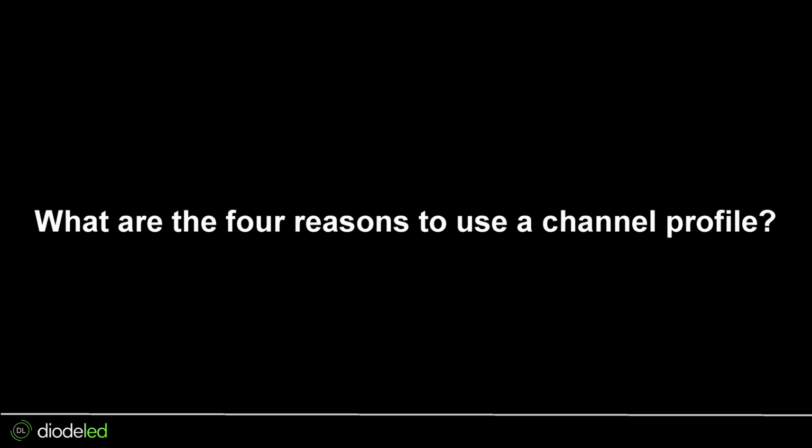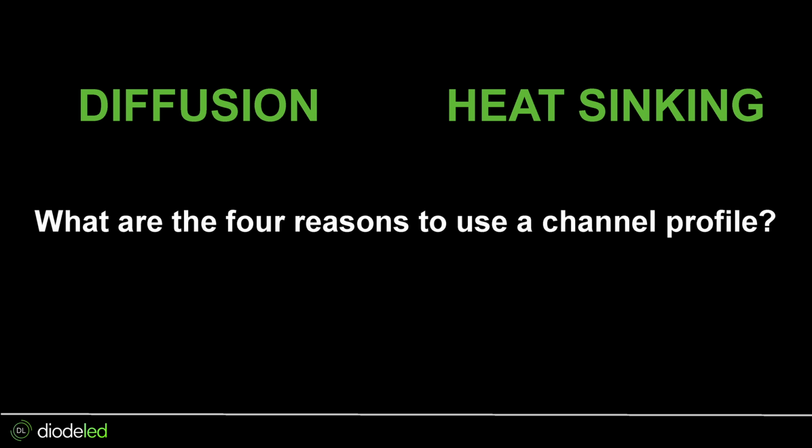All right, so we're gonna get started with the basics here. Really, what are the 4 reasons to use a channel profile? There's probably more than 4, but in my opinion, number 1 is obviously diffusion. Then you're gonna have heat sinking. So heat sinking is from the aluminum channel. That aluminum channel helps dissipate the heat and pull the heat away from the tape light. As we all know, the death of LEDs and component drivers is heat. So we want to always do our best to pull that heat away.